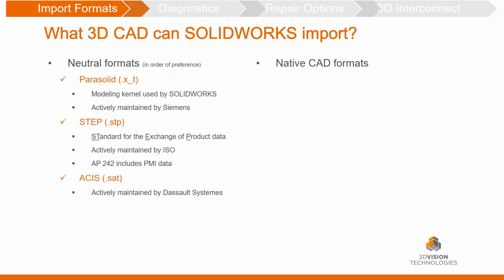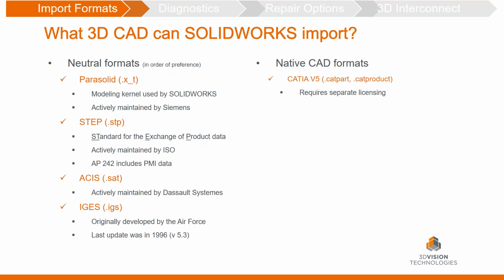Third on the list, we're going to list the ACIS kernel. That's actively maintained by Dassault Systemes Corporation. And then we can't go without mentioning IGES. That's been around for a long time. It was originally developed by the Air Force, but the last update was in 1996, which was quite some time ago. So if at all possible, we tell people to try and avoid that neutral file format.